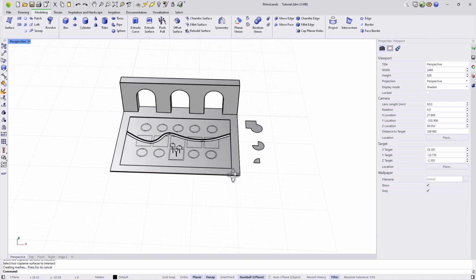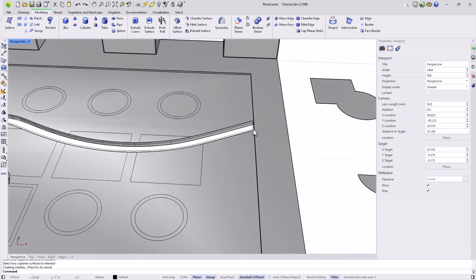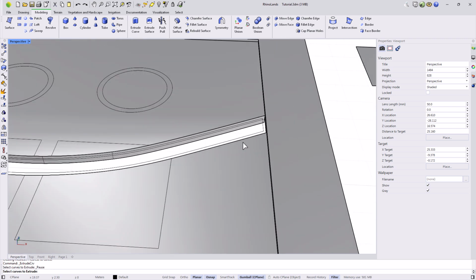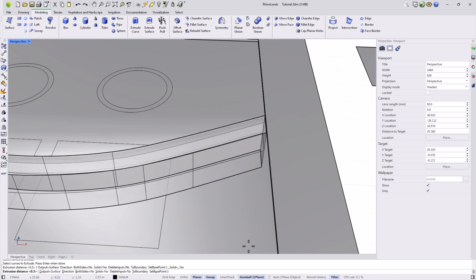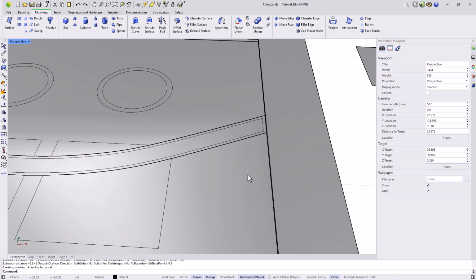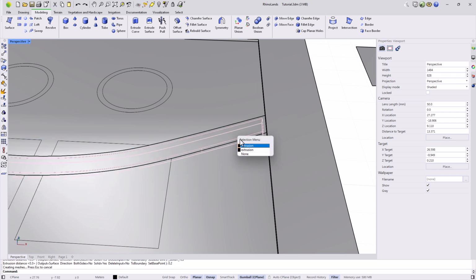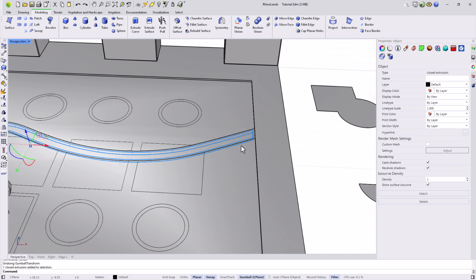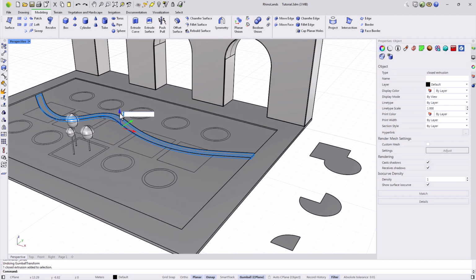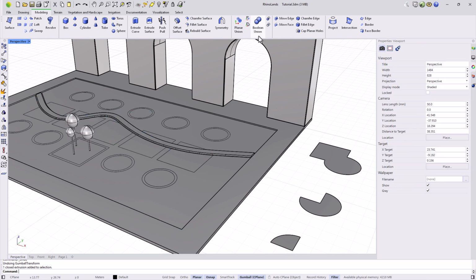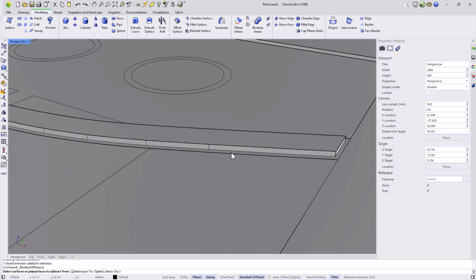As we have seen now, for example, we can put it into practice by creating the walls of this water pond. I'm going to create 2 different solids. One with an extrusion from the outer curve and another extrusion with the inner line. Now I have 2 volumes. I'm going to move the inner volume a bit. And now I perform a Boolean difference operation to subtract one volume from the other.